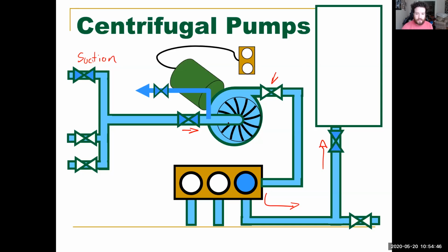All right, now, like I said, with centrifugal pumps, the big thing to know is that they always have to be primed. All right, centrifugal pumps always need to be primed because they're not self-priming. They're not going to be able to pull in a volume, whether it be air or liquid, and prime themselves. So what you have is your priming line.